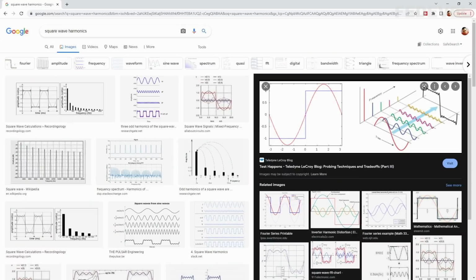Also keep in mind that the square waves or signals with very sharp edges, for example, when your chip is communicating with all the other chips or when it is controlling I/O pins or accessing memory, these kind of sharp signals, they contain all the kind of frequencies. So to build or design a reliable system, you need to be able to deliver enough power for all the frequencies your chip needs.